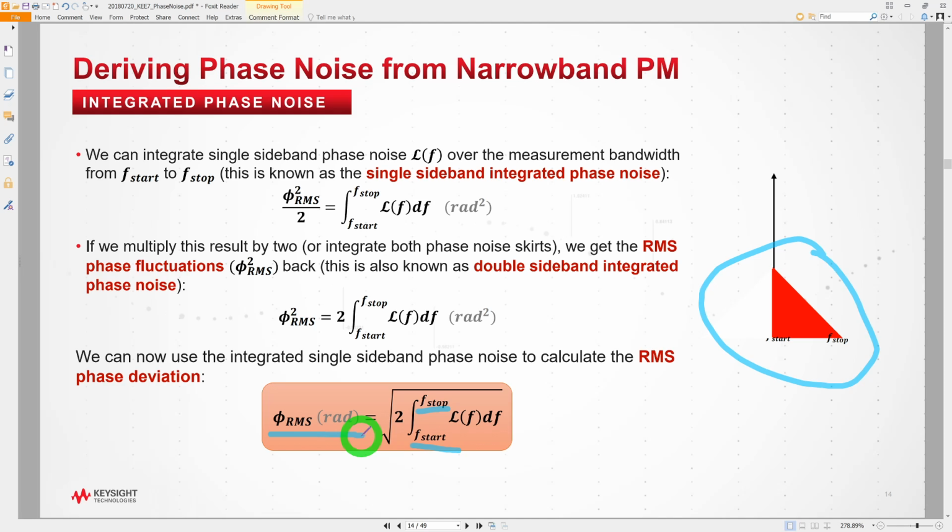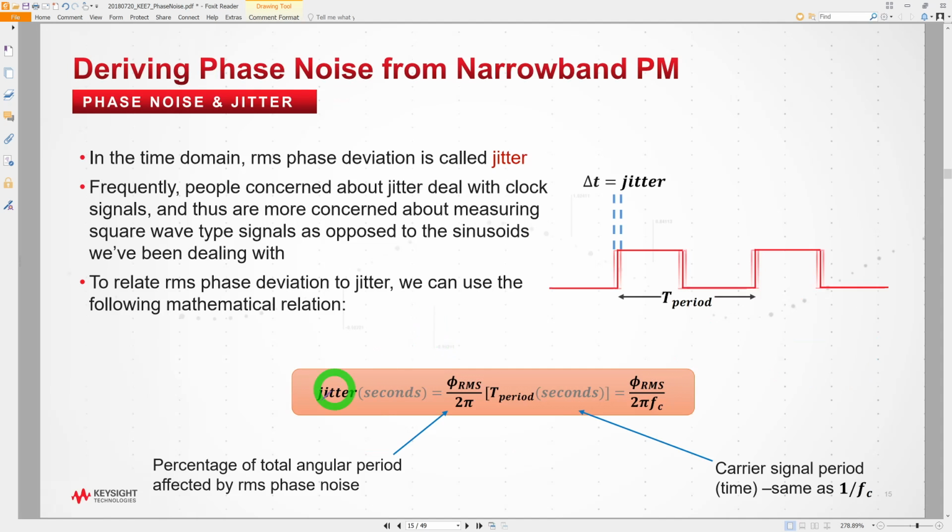Now, you don't typically hear jitter when people talk about phase noise. Jitter is often reserved for data communication, on data that comes through, defining how the edge transition of the data changes over time. I'm going to do a separate video on jitter once I have some instrument that I'm waiting for. Then we can talk exactly about how jitter works and how you can decompose jitter, and that's a whole other topic itself. Nonetheless, you can calculate the jitter in seconds by taking the RMS value and multiplying it by the period of the frequency.